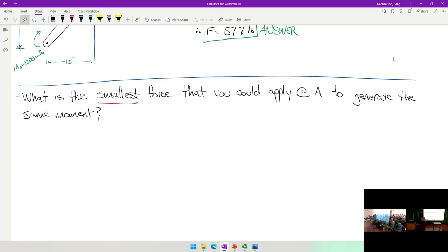Perpendicular, right? If I had a bolt that I needed to tighten or loosen and I had a bar out here, I would apply that force perpendicular to that bar, right? Because that's going to give me the most effect. Make sense? That's where I'm going to get the most bang for my buck, as it were, in terms of actually getting the job done, applying that torque or moment. Again, moments versus torques, I could talk about that all day. It's really just a terminology question.